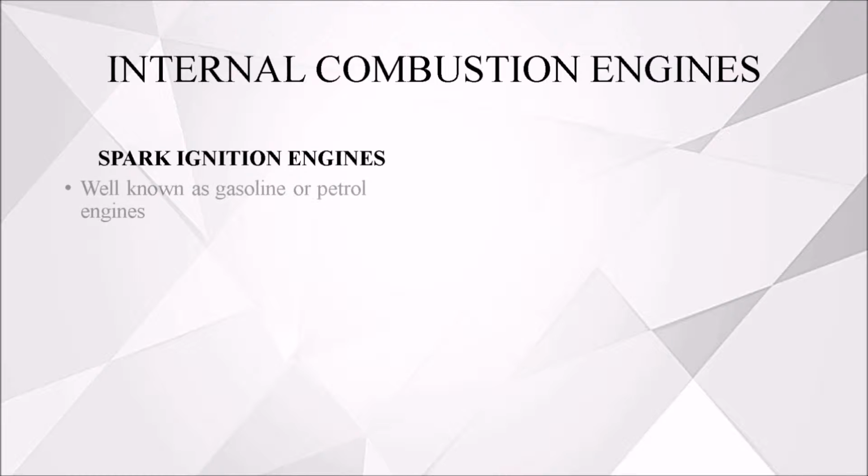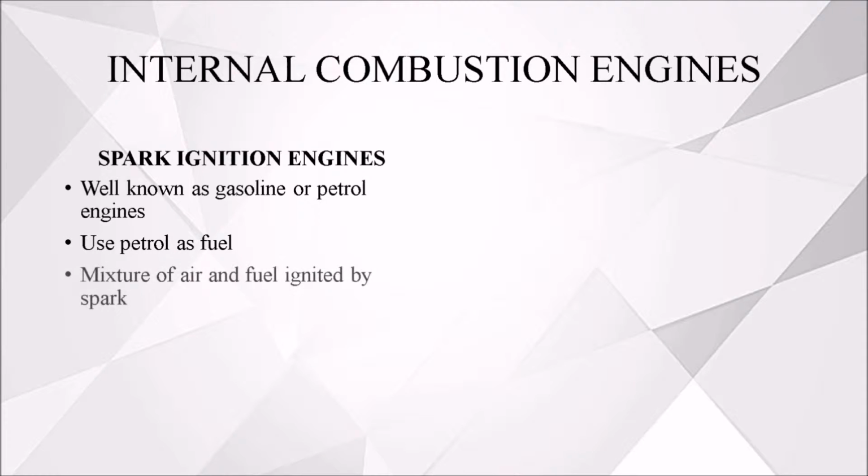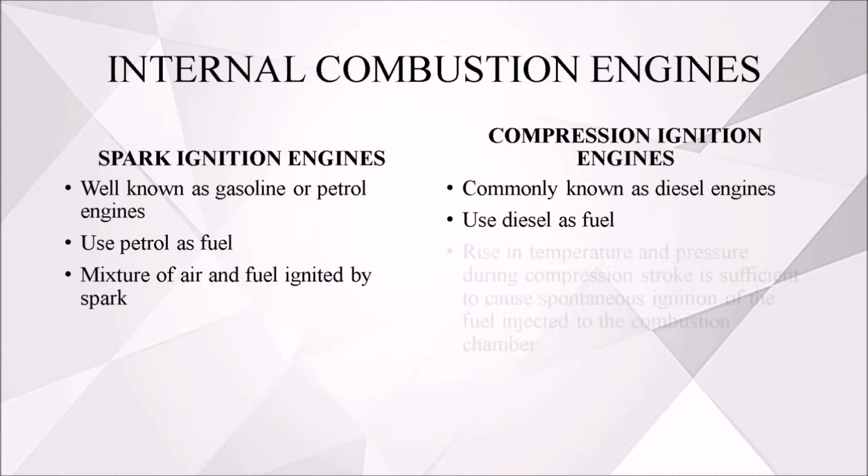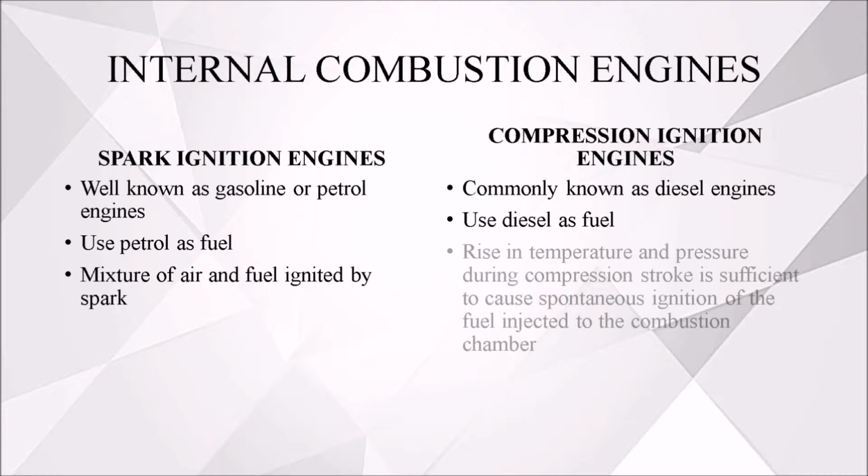Internal combustion engine, spark ignition engine, well known as gasoline or petrol engines. They use petrol as fuel, and the mixture of air and fuel is ignited by a spark. Compression ignition engine, commonly known as diesel engines, use diesel as fuel. The rise in temperature and pressure during the compression stroke is sufficient to cause spontaneous ignition of the fuel injected into the combustion chamber.